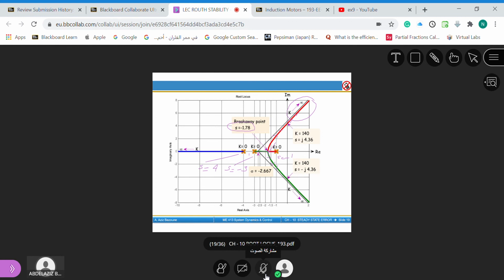The root locus is just on the left of an odd number of singularities. This is the first singularity, this is the second singularity, this is the third singularity. So -3.5 is not part of the root locus. Now we found this, guys.